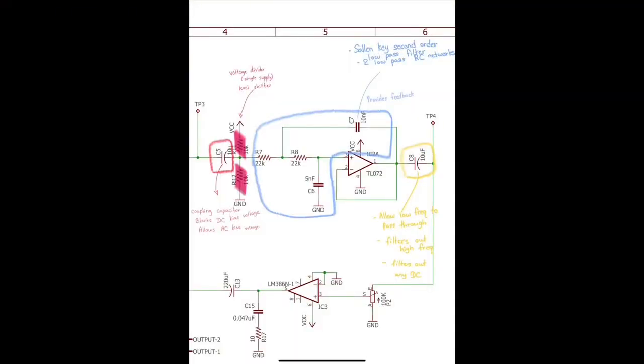Now for stage 3, before the input is delivered to the op-amp, it first goes through capacitor C5. It lets the heartbeat signal through but blocks unwanted DC voltage, ensuring a clean centered signal is sent for filtering. Then the signal passes through a voltage divider of resistors R11 and R12, which also serve a secondary purpose as a level shifter to prevent clipping of the output. The output is then sent to IC2A.